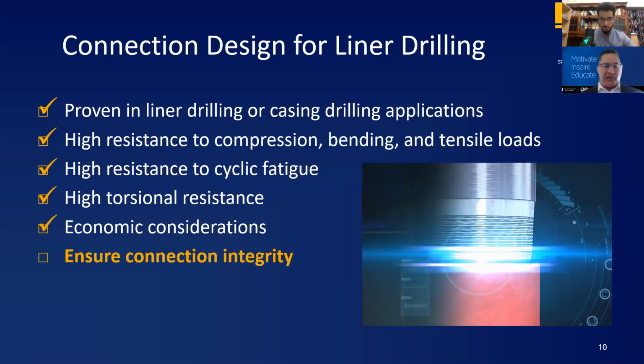Economic considerations are very important, of course. I know I work a lot in U.S. land applications, and they typically run some type of buttress or modified buttress. But then again, people that run torque rings in buttress or 8-round connections, the torque rings do give you added torsional resistance, but they do nothing for fatigue resistance. So think about that for a section.